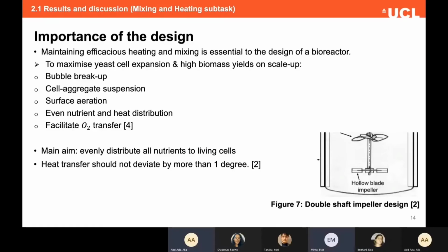We selected optimum conditions to maximize protein synthesis in order to obtain the maximum yeast concentration for our bioreactor. This reduces overall production costs and allows for scalability. Different microenvironments due to inefficient circulation of waste product can lead to cell death and trigger transcriptional induction of alternative cell genes. By microenvironment, we refer to temperature gradient, toxic waste gradient, areas of depleted oxygen, or uneven distribution of feed. Overall, an even distribution of feed and nutrients was to be prioritized in the design because temperature in fermentative processes should not deviate by more than 1 degree Celsius.